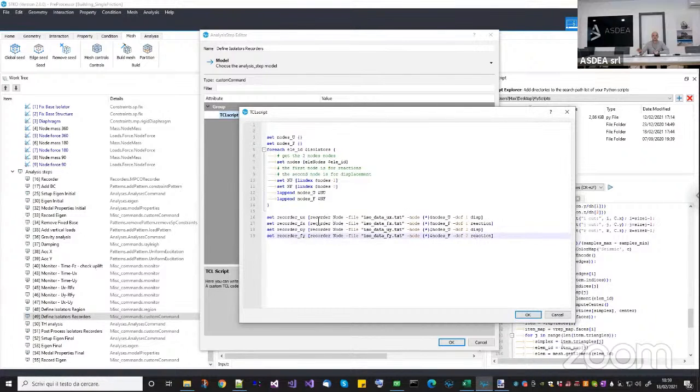Okay, now I'm pretty sure you've always seen the recorder command, but you have never seen this kind of operation here, because the recorder command in OpenSees actually gives you an output, okay? Basically, no one uses it because it is never needed. But in this case, I need to grab the result of this command, and the result will be the ID, so the tag of this recorder.